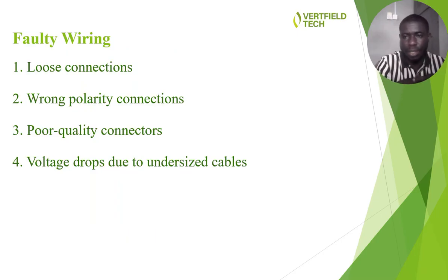Faulty wiring. Yes, faulty wiring will come from the aspect of wiring your solar panels directly to your solar generator box, or from not having the right connectors to use, or from not being professional in using the connectors.